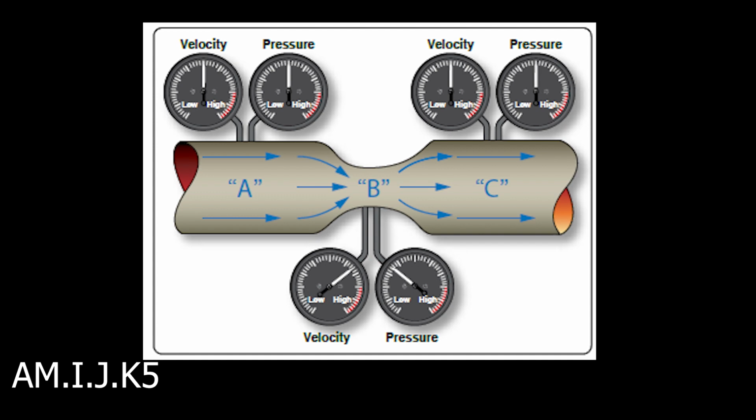As fluid flows through the Venturi tube, the static pressure of the fluid decreases at points where the velocity increases, according to Bernoulli's principle. This principle states that the static pressure of a fluid decreases as its velocity increases, provided no energy is added to or taken away from the fluid. The wide section of the Venturi tube has low fluid velocity and high static pressure, while the narrow section has high velocity and low static pressure.